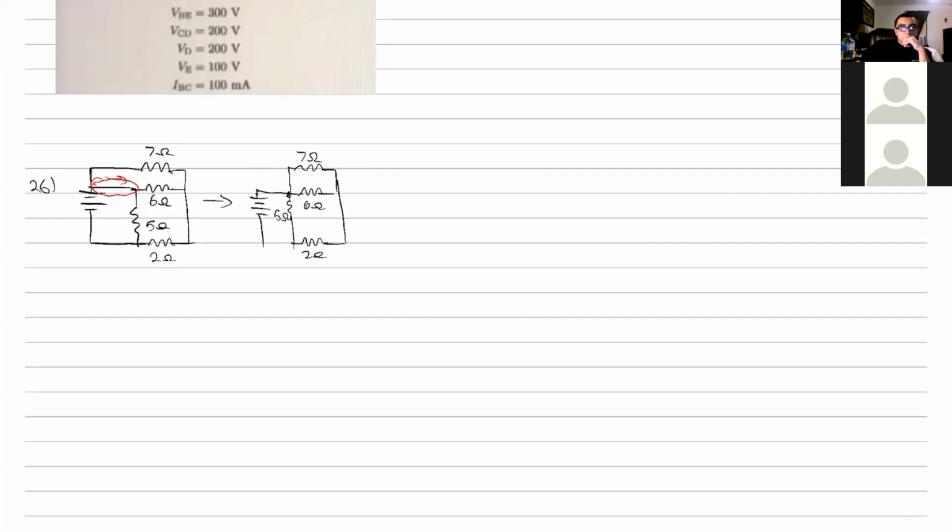All right, so does everyone see what I did there? All I did was redraw the circuit. This node is still connected here. All we're doing is reshaping it essentially. It's not changing how the circuit is physically connected. So we just shifted this node over a little bit to the right. Now looking at this, we have a very obvious parallel connection here.